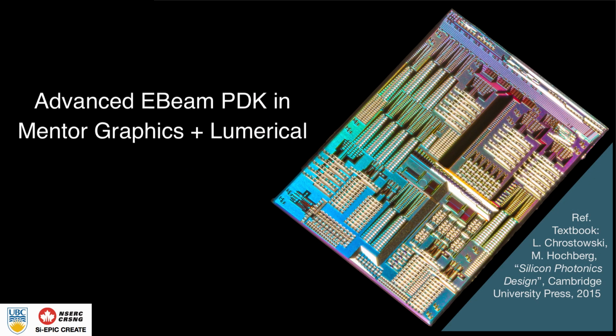In this unit, we will go through how the schematic-driven design method works in practice in order to implement a layout that is ready for fabrication. We have a PDK for the e-beam process, which contains all the elements necessary to simulate, lay out, and verify a circuit. We think of this as an advanced PDK. While the components themselves may not be the most advanced, it is the full flow methodology that we consider advanced.